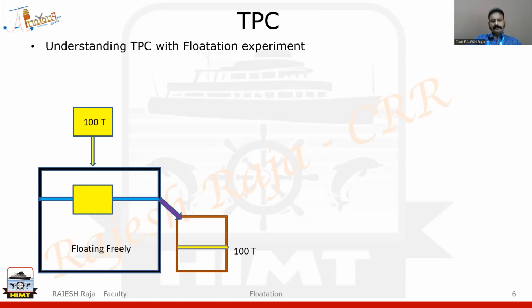So that was our old flotation principle. Now let me add 20 tons on this vessel. So very evidently, it's going to sink more. There's going to be more displacement. And for example, let us say this sinkage was exactly 1 centimeter. So if I have this 1 centimeter sinkage, you all should realize that that means there's a change of displacement from 100 to 120. So I'll get that same extra water here also. Now this water in the overflow container will weigh 120 tons.